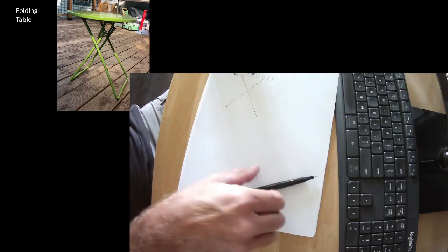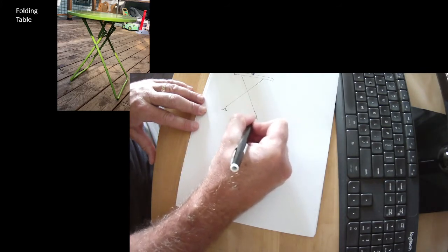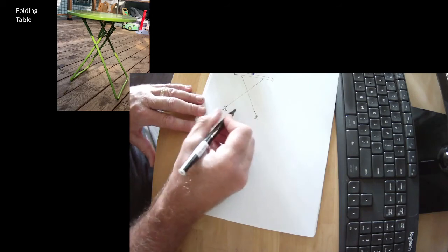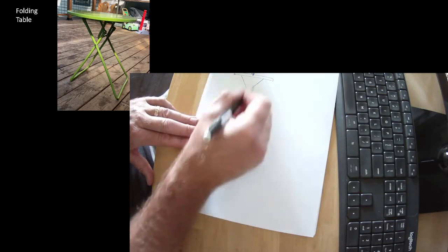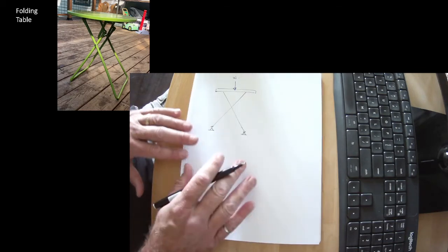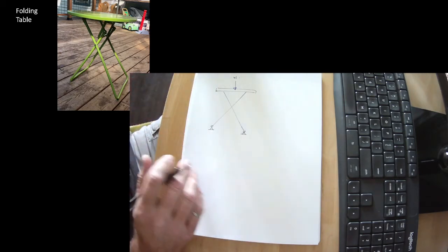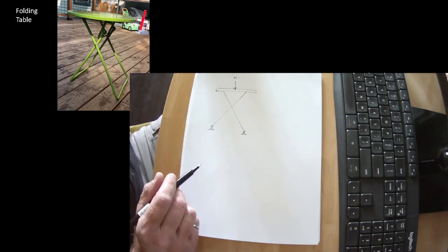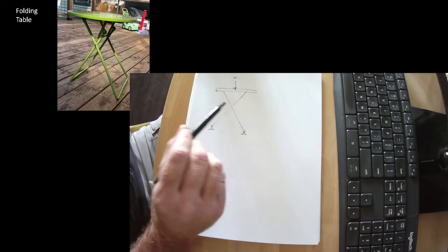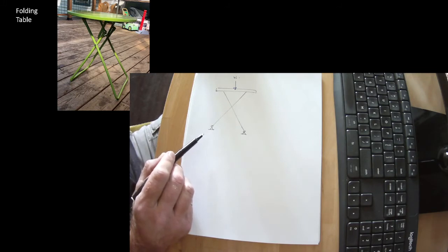As soon as anybody draws triangles, we have an inclination to think it's a truss, and to think that because it's triangulated, there's no bending moment. Because we're taught with trusses, you triangulate your truss and then you don't have any bending moments, and that's what makes it effective. And so people draw an X and they say, triangles, it's a truss, I don't have any bending moment. But in fact, this is not triangles, it's an X, and this thing behaves quite differently.